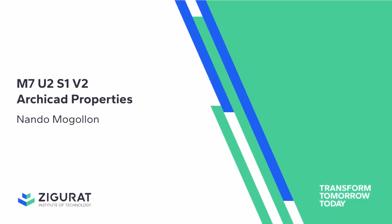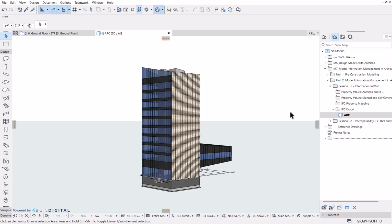Let's start talking about property values in ArchiCAD. ArchiCAD properties are available to every single model element as long as it's been classified. So let's take a look. Let's go to the menu options and Property Manager.